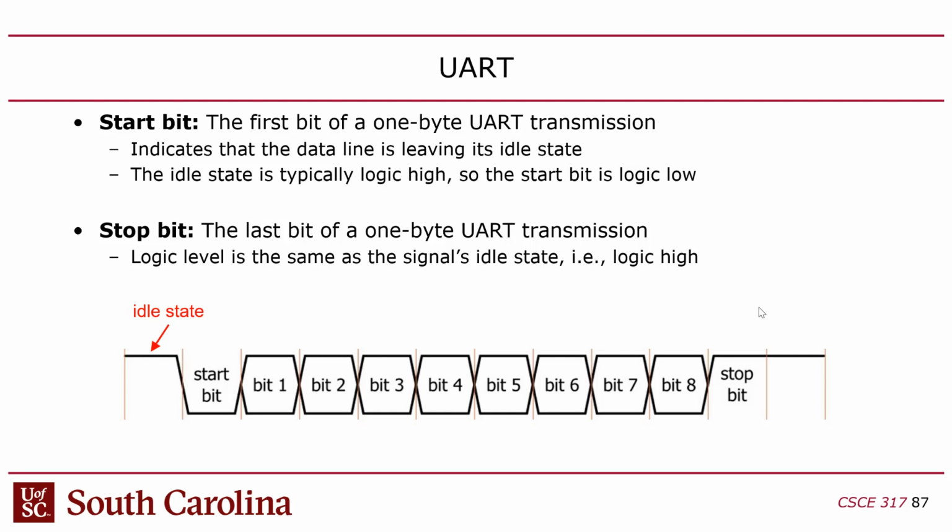So you have a start bit that is 1 bit time of the data wire being active, or logic 0, that indicates the starting time of the transmission. Then you may have 8 bits that are sent across. UART normally transmits 8 bits at a time through the channel, like SPI, and then you have a stop bit, which is when the data channel is high for 1 bit. Okay, so the start bit is low for 1 bit time, and the stop bit is high for 1 bit time.